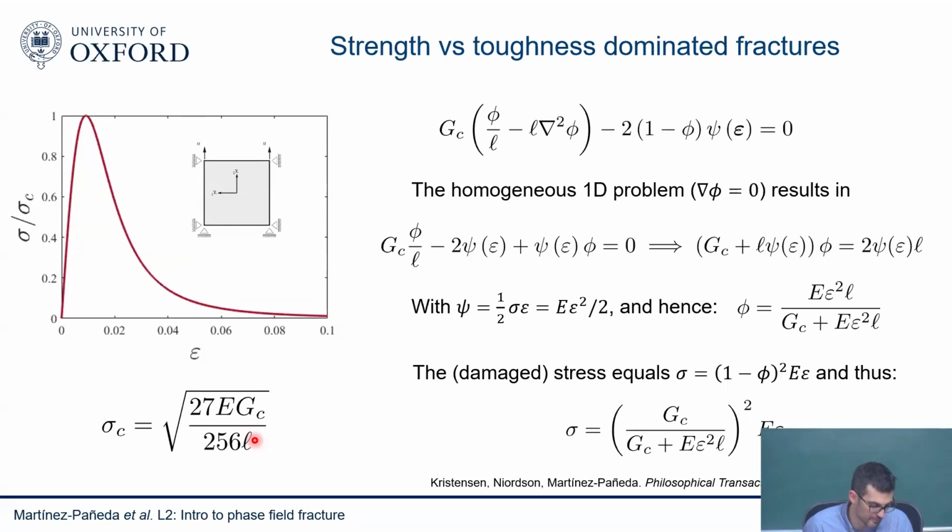Yes, so there's a bit of debate on that. It's a good point. People like Bažant would argue that fracture mechanics doesn't hold that well in concrete unless you have very large samples, because they argue that in the fracture process zone you get a lot of extensive micro cracking. There's a bit of debate on that. I'm not going to take sides.